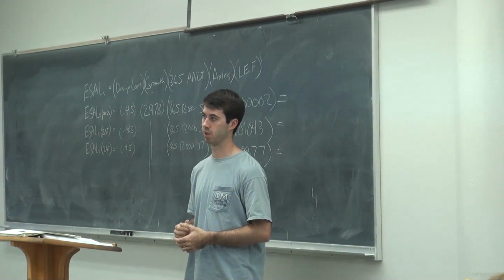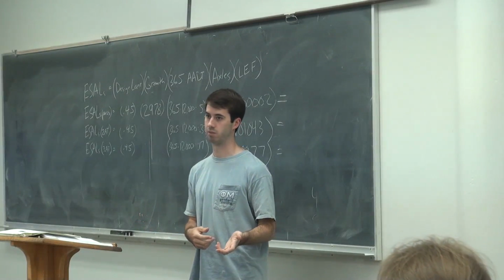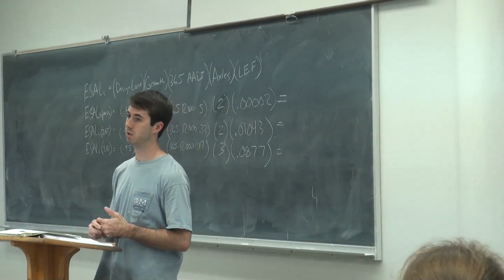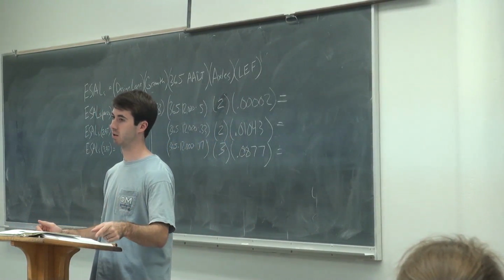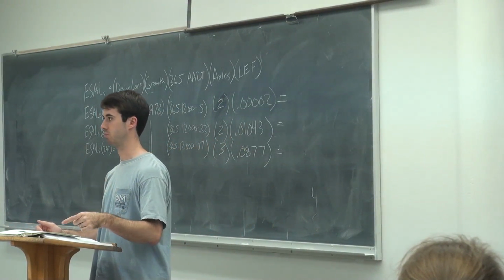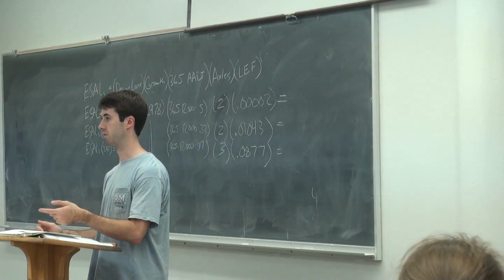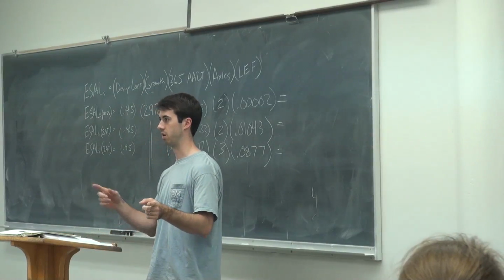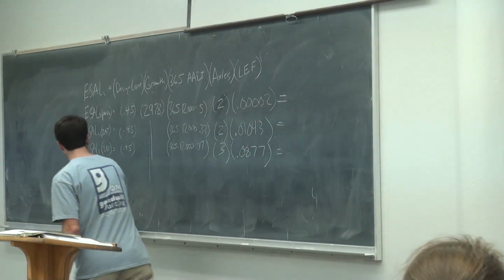That means that you got 100 grams of asphalt mix, 5 grams of asphalt binder, 95 grams is aggregate. That 5% is out of the total mix. So if you say I got 100 grams of aggregate and I want 5% binder, it's not 5 grams, because that would give you 105 grams of mix. So now your percent binder is 5 divided by 105. Does that make sense? You don't want to write that down?